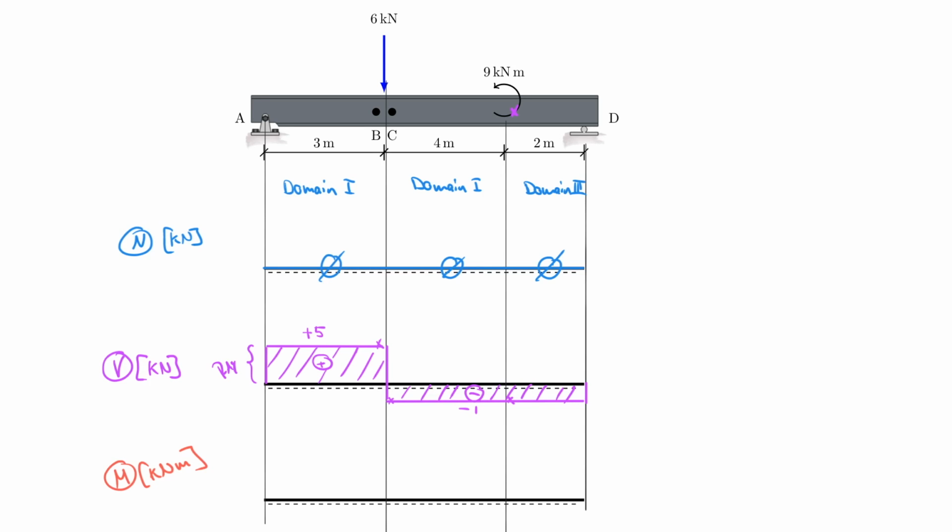And now I can find my values that I calculated first for B. What did I calculate? I calculated that to be plus 15. So let's pretend that's right there. And then at C, I also calculated it to be plus 15. So of course, in reality, it is at the line. So I'm going to erase this real quick and actually put the X directly on the line. So I pretend that this here is plus 15.